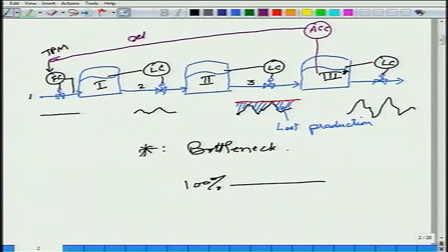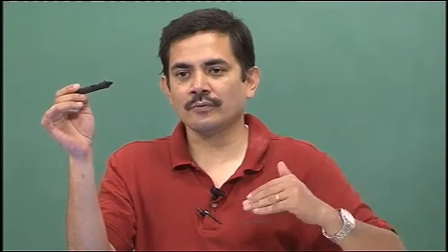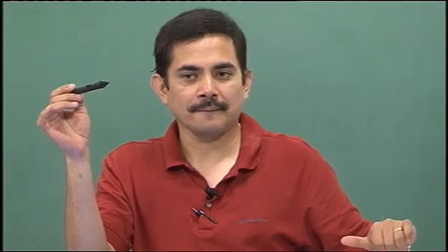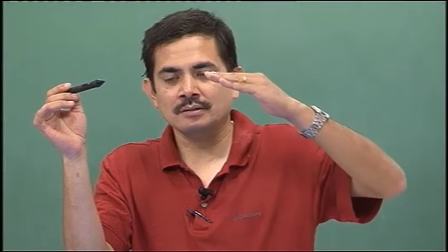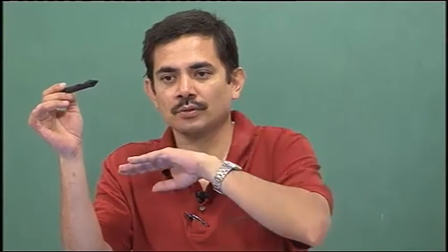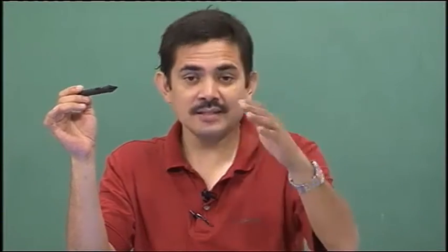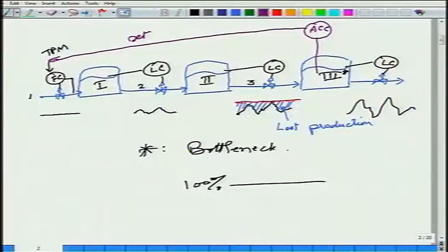So it is setting the throughput. This is what the operator is doing, right? He is looking at the active constraint. I am far away from the constraint being active, jack up the throughput, right? I am approaching the active constraint value, well, reduce the throughput. Violation is not acceptable, because what that means is then unit 3 will have to be shut down, and if unit 3 has to be shut down or some corrective action has to be taken, that represents a significant economic loss. Okay. All right. So this is what the operator is doing.